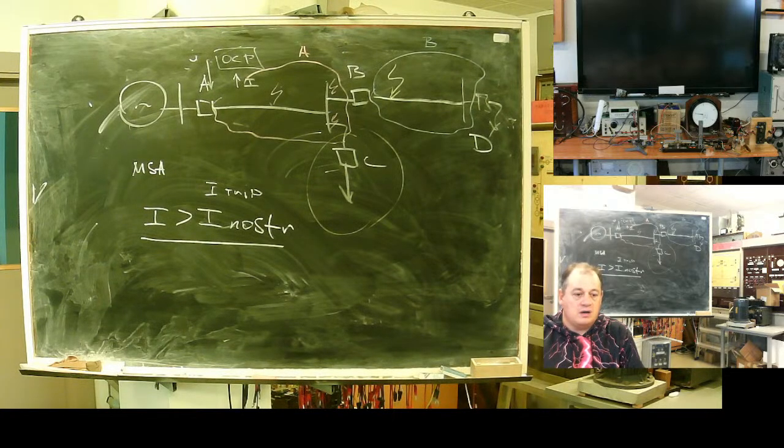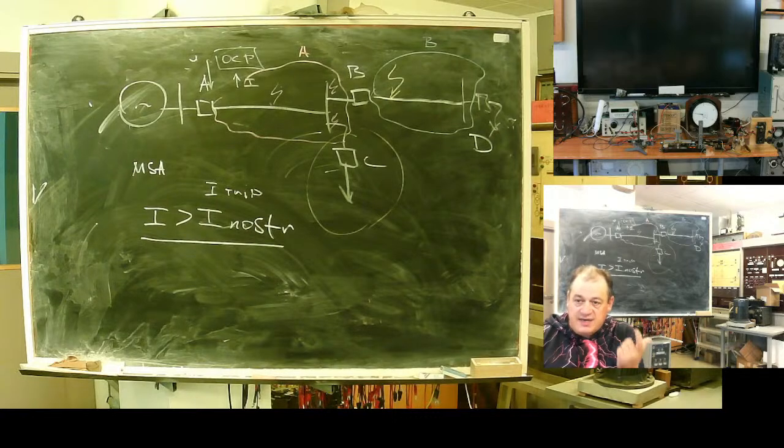So our basics: sensitivity, ability to sense internal faults; selectivity, ability to not trip falsely on external faults; reliability, this means being ready to operate, to protect with a high level of reliability within a prolonged period of time; and economic adequacy.